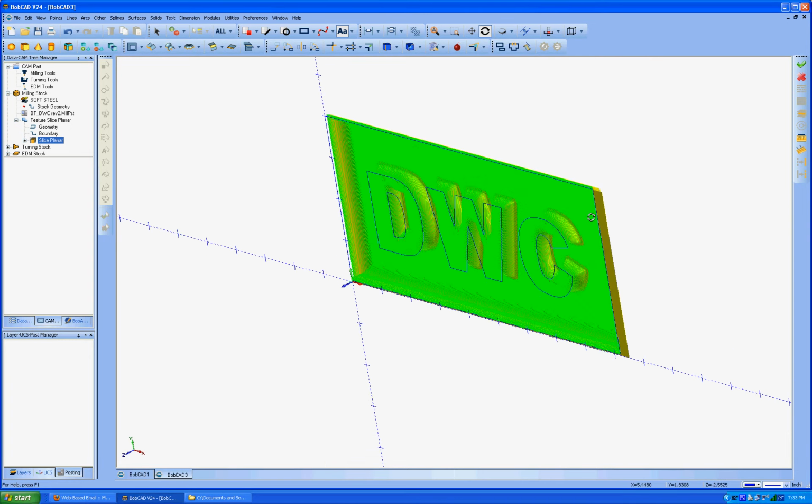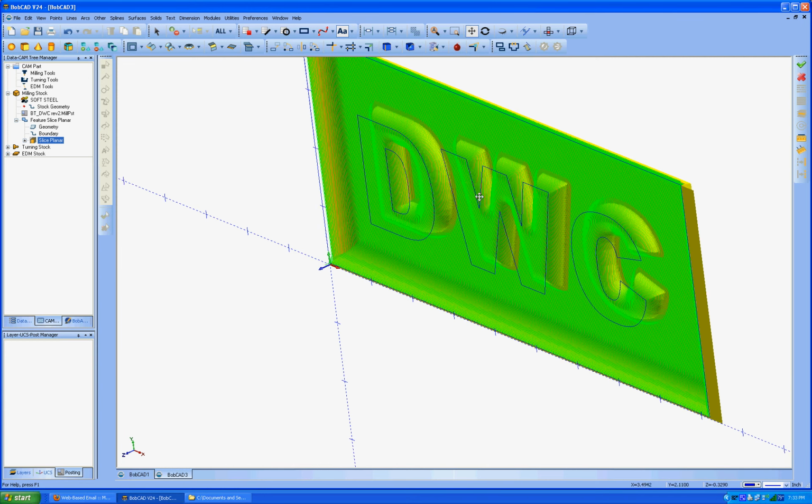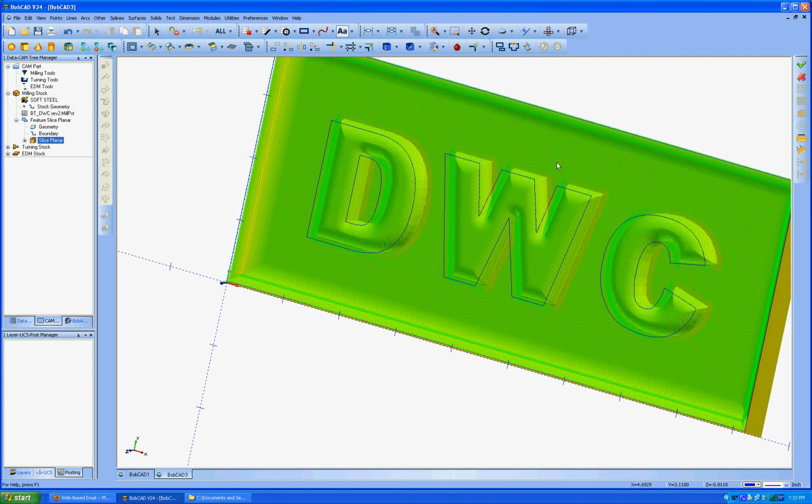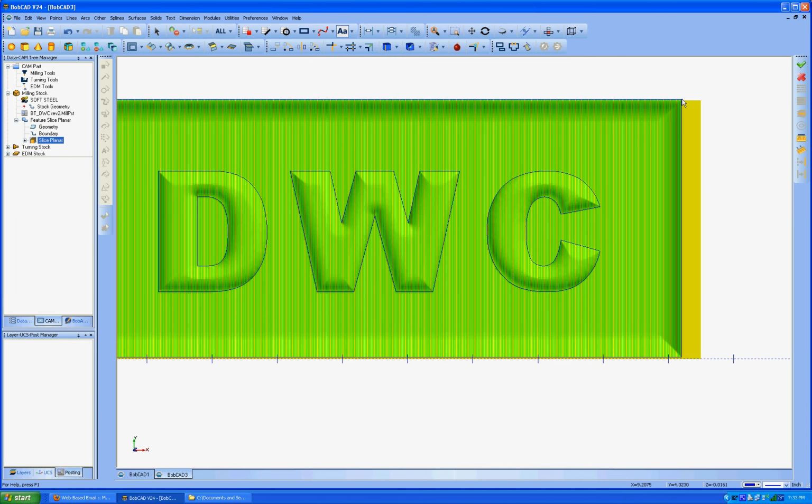So what it's going to do, make this 0, it's just going to start here, go down, go over 15 thousandths and go back up, and just go back and forth and follow the contour the way the shape of it is, and then it'll give you that look. So that's a tool path. From there, you would basically just do a post and save.